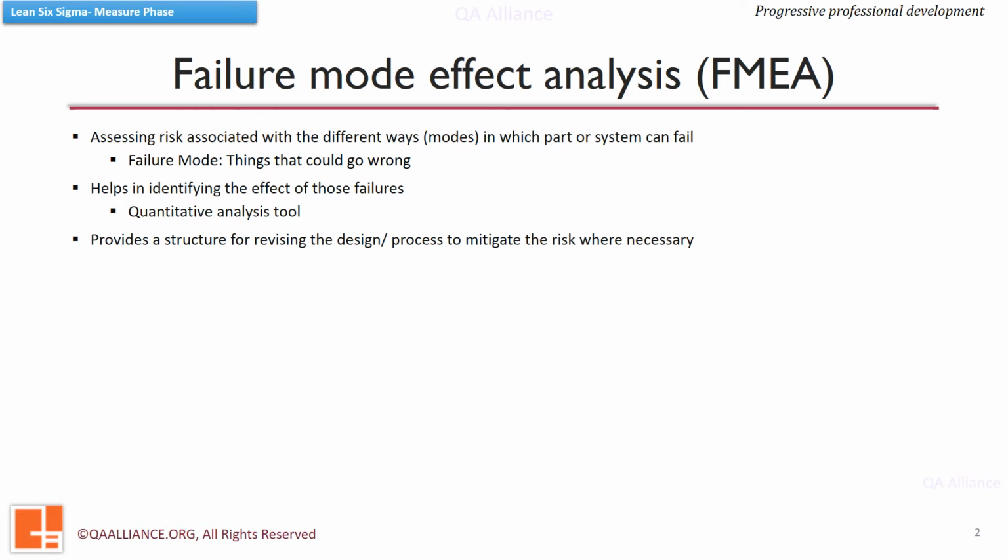It is a kind of inductive process and involves questions like, if this failure occurs, then what? It is a method for quantitative risk analysis and is useful in comparing designs. FMEA also helps in process improvement as it identifies and eliminates concerns early in the development of a process or design. Since it focuses on prevention, eventually we also get an improved internal and external customer satisfaction. In essence, it points to process failures that are most difficult to detect.